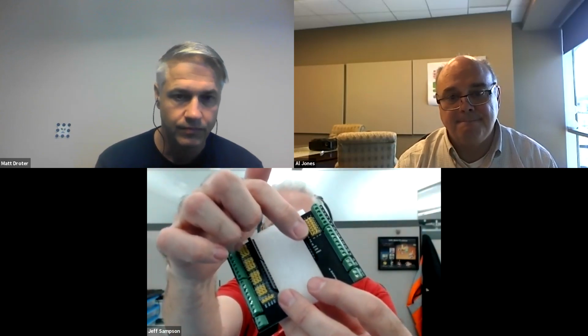I thought originally it would go on top, and the screw terminals would be right in the middle, but it doesn't fit that way. So if you're going to use it on the real Arduino, it's got to go like this. And the more I looked at it, any of these yellow ones here says it's got 5 volts, ground, and a signal on each one. These right here are just for the analog, so you've got your 6 analog signals there, and the ones on this side of the board look like they're all the ones that say digital.